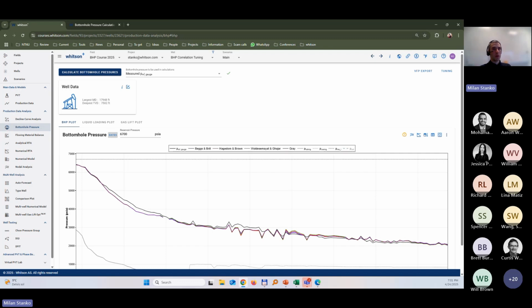With the amount of foam, they have some surface tension change between the liquid and the gas, and that surface tension change gives you a different holdup. But that's not implemented here in the software, so at this time I can't think of a workaround to do it, but that will be the effect it will have. Thank you.